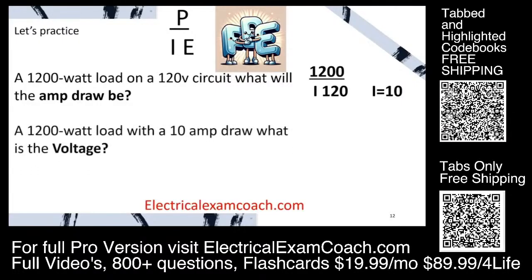We have a 1200 watt load with a 10 amp draw. What is the voltage? Well, let's plug in what we know. We know our wattage and our amperage, and all we're looking for is to solve our voltage.